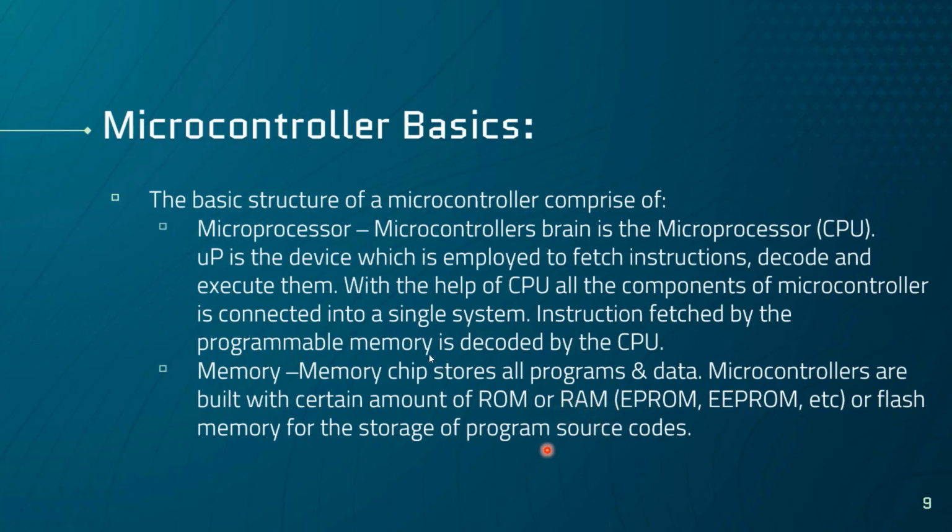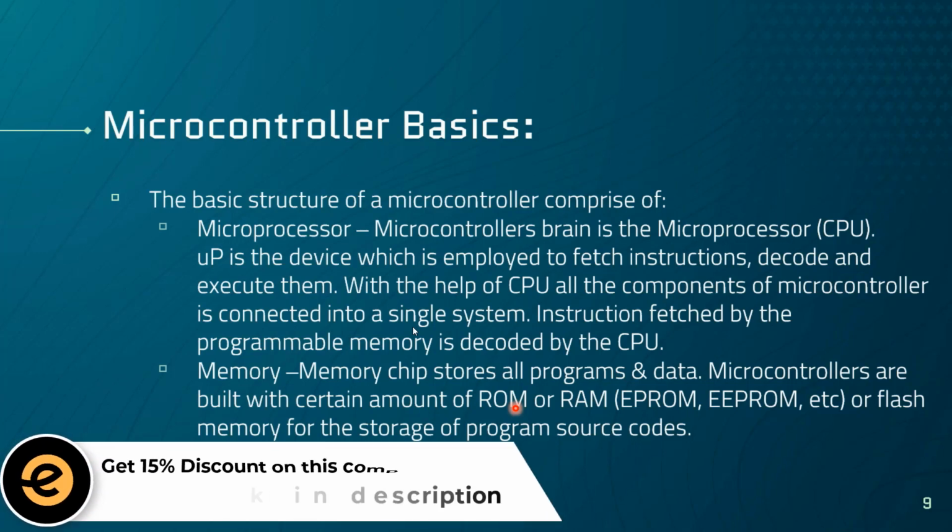The main difference between the ROM and the RAM is that the ROM is typically read-only memory. So the instructions are saved whether there is a current supplied to the microcontroller or not. So it's basically non-volatile, which means that if the current is cut off from the microcontroller and then it wakes up again, the code is still there. It can still execute the same instructions.